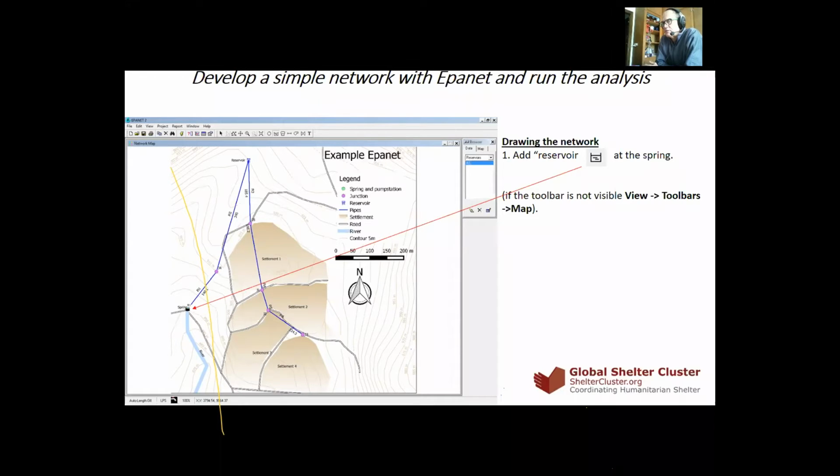Ah, okay. It's not geo-referenced, but it's on scale. But if you have auto length on, it will not be on scale. So auto length must be off, and then you put the length of the pipe yourself, so the map is as a reference only. Thank you. Yes, it's much easier. Theoretically, you could do it without a map. That's not a problem, but it will be more complicated to understand the error if you do it without a map.